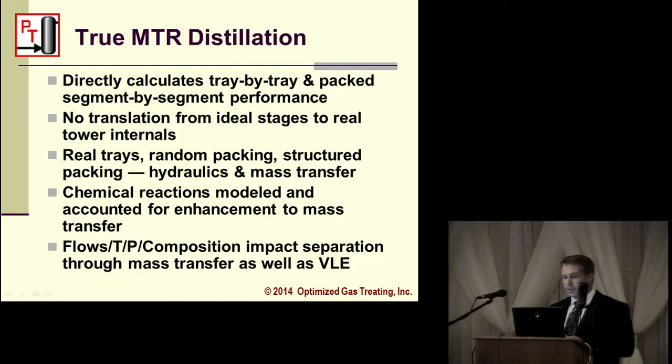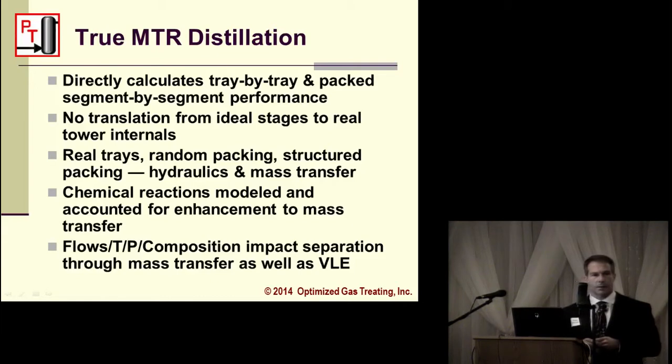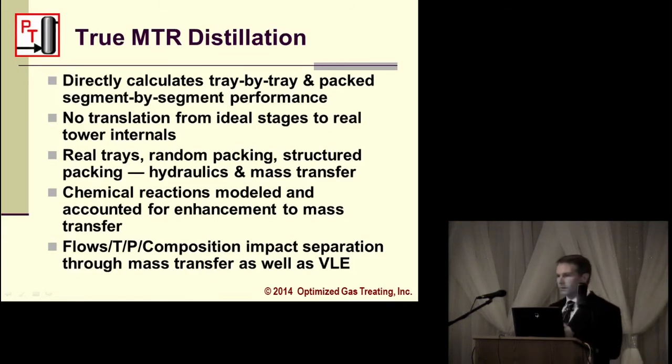In ProTreat, there is no translation from ideal stages to real tower internals. We start with real tower internals. So with that, you get the hydraulics computed at the same time the mass transfer is computed. They're coupled, and that's important.